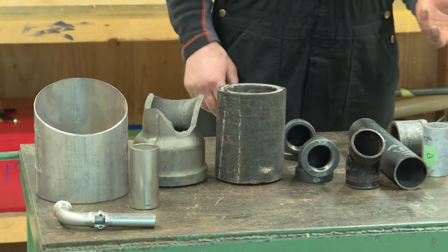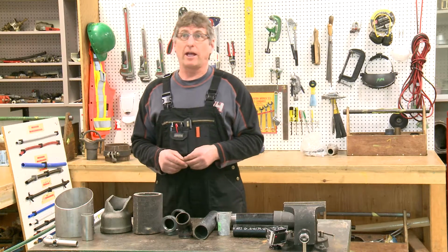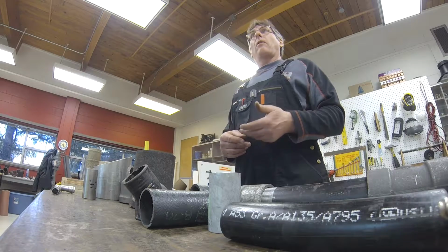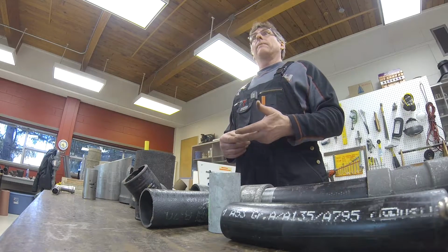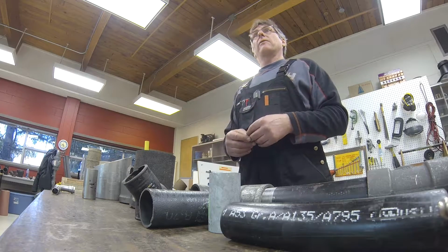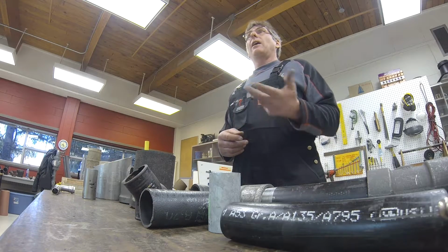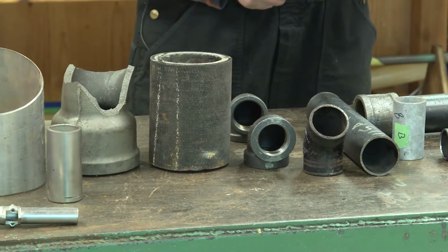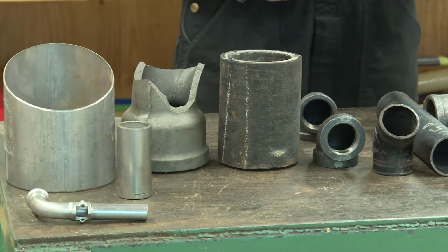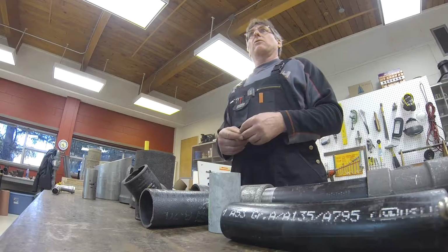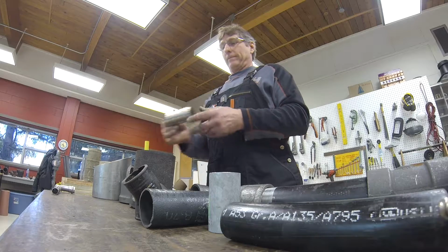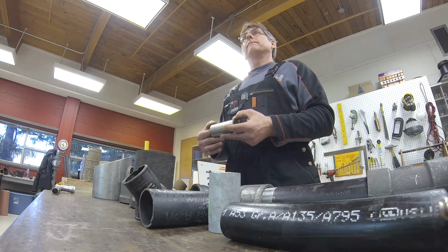Inconel is another alloy, I don't have a piece of it here today, which has about 40 to 70% nickel and 14 to 30% chromium, with varying compositions of other elements. It's highly oxidation and corrosion resistant, with good strength at high temperatures and pressures. It's used for high-powered exhaust systems and turbines. It looks very similar to stainless steel, slightly duller in color.